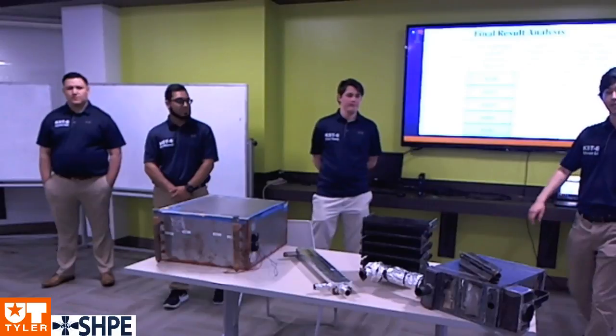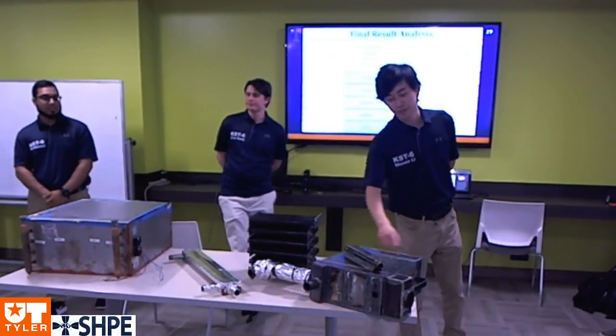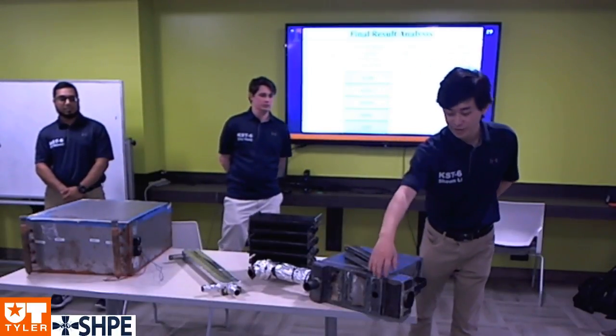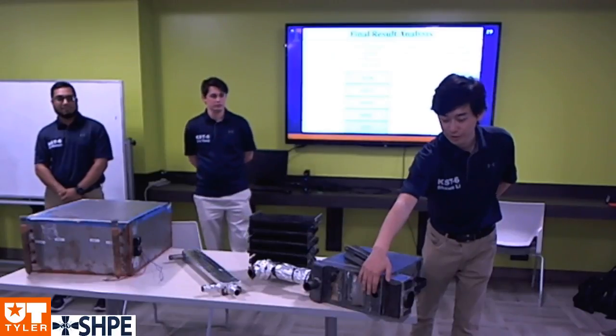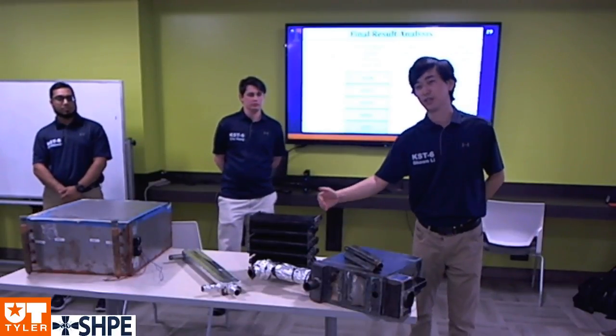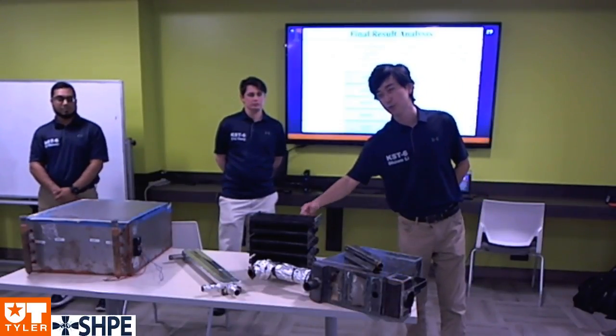Are you asking specifically for the reason why this top and bottom is split? That's actually to fit in the manifold too. Both of these sections go into the manifold, and as you can see, we have a hole over here for the shell sides. So this is to make sure that the tubes do not come in contact, that air flows correctly in the shell over the tubes and not into the tubes themselves.